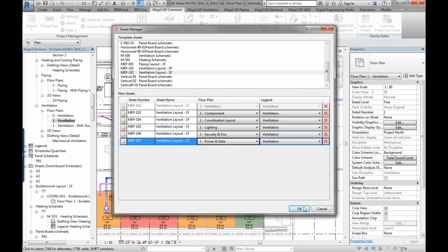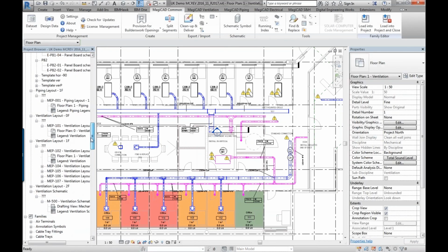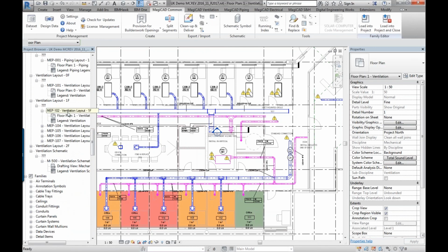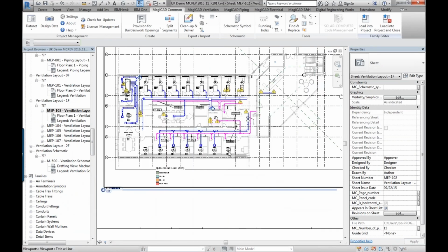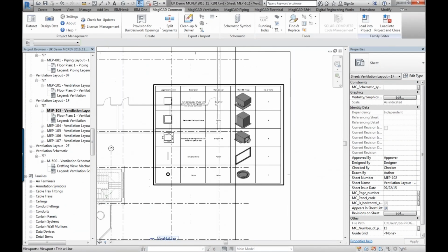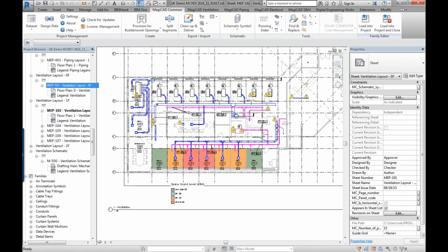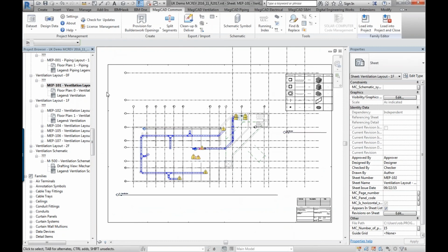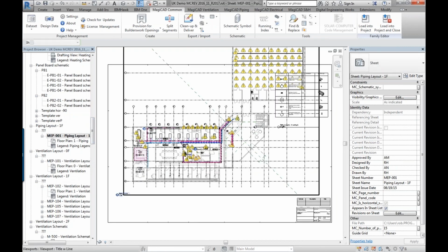automatically. And also importantly, it will align every single view exactly the same. You can see there's the legend that's pulled from the previous sheet, and it'll line everything up. So when you look on this sheet here, everything is perfectly aligned. So as you build up through the project, instead of having to laboriously create sheets by dragging stuff in from the left hand side and dragging the sheet in, it'll just create the sheets automatically, all lined up for you. So it should be a time saver.